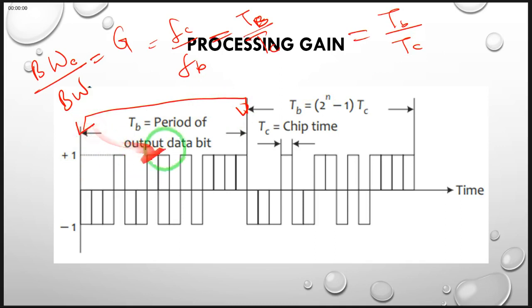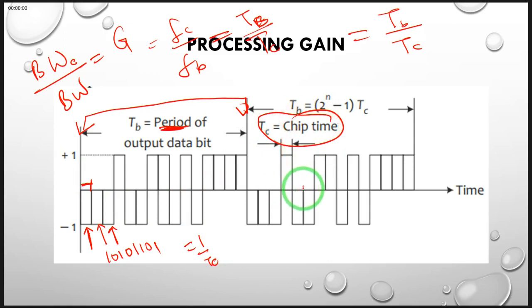This is your pulse period, but the spreading code has very many pulses of zeros and ones, produced from the spreading code, which is a combination of ones and zeros. We have already said that the chip rate, which is the rate at which the spreading code is arriving, is determined by 1 over TC, and TC is just this one period here. This is the chip period or chip time. That is how you obtain the gain, which is sometimes referred to as GP.